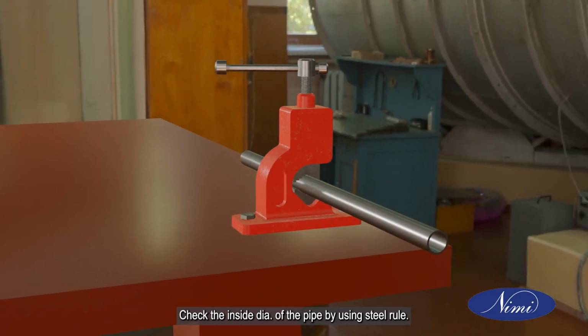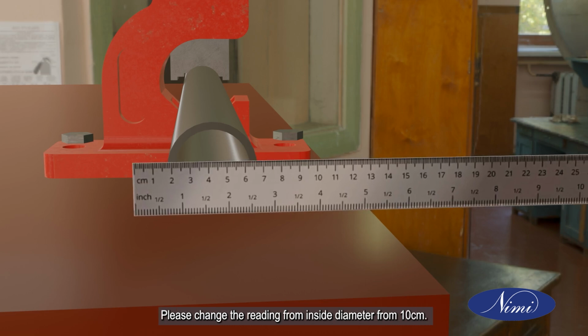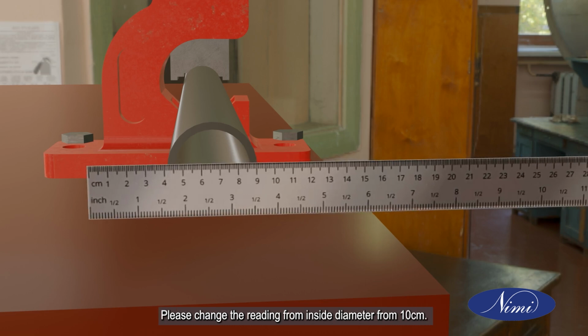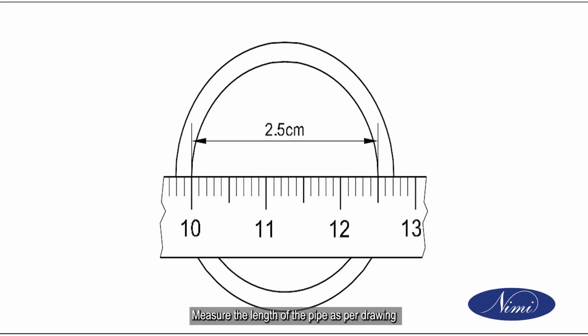File the pipe ends and check up its squareness. Check the inside diameter of the pipe by using steel rule. Measure the length of the pipe as per drawing.